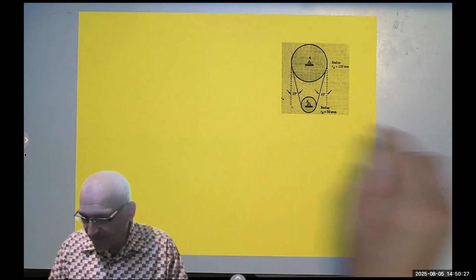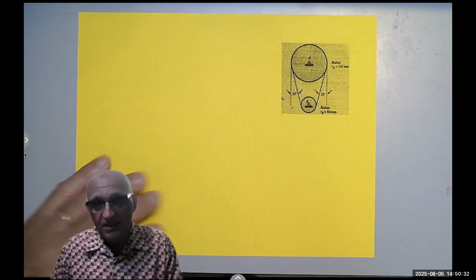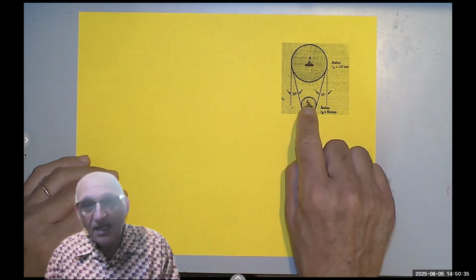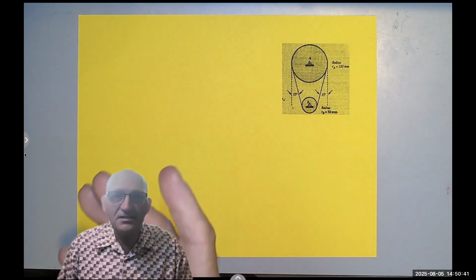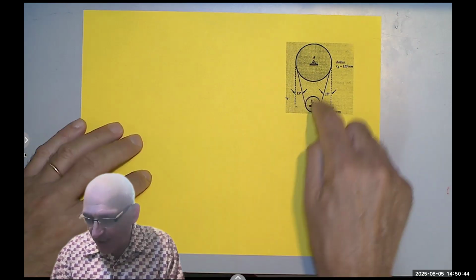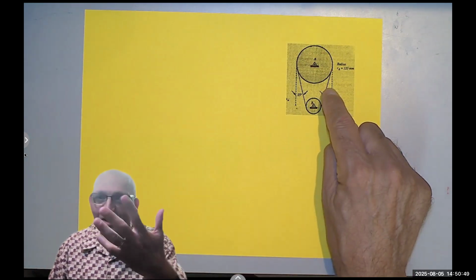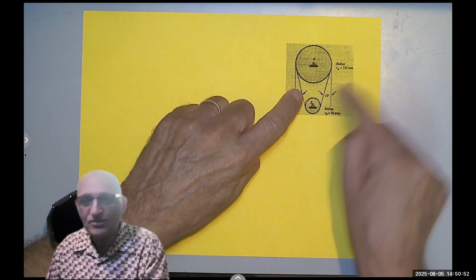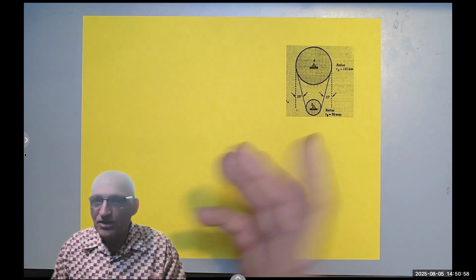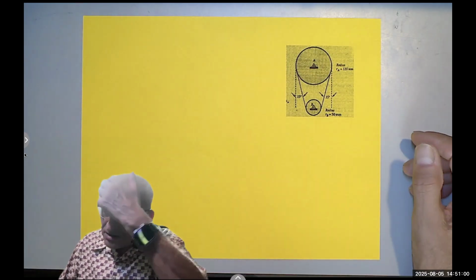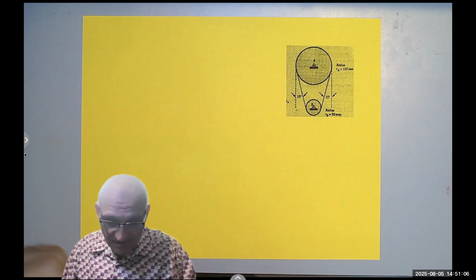So here we have a motor attached to point B, the shaft here, and this thing rotates. It doesn't matter which direction. Why? Because if it rotates clockwise, then this would be the higher tension, which we call T1, but I call T2, and this would be the lower. If it rotates in the opposite direction, that would be the higher and this the lower, but the magnitude would be the same. So it really doesn't matter which direction the pulleys rotate.